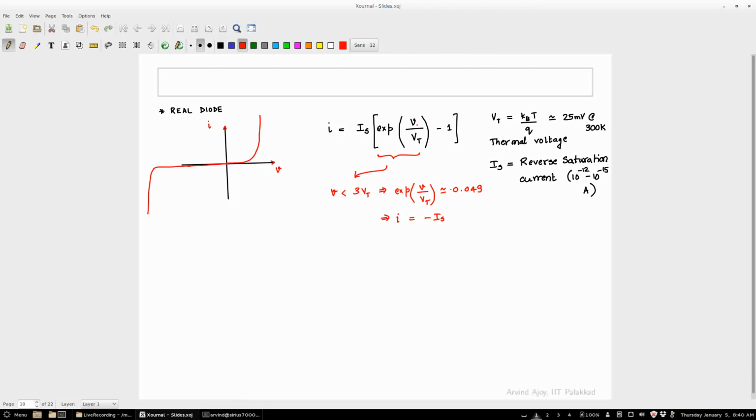No, right? So this is a model. The real diode is the real diode. So the way I motivated it is not possibly the correct way of doing it. There is a diode like this, and you can model the diode by this equation. In fact, we forgot to put in one factor, which is a source of non-ideality, a factor called n. We'll see what n is. It's a number. For an ideal diode, n is 1. For certain diodes, n is 2. It's usually between 1 and 2. So that is your real diode.